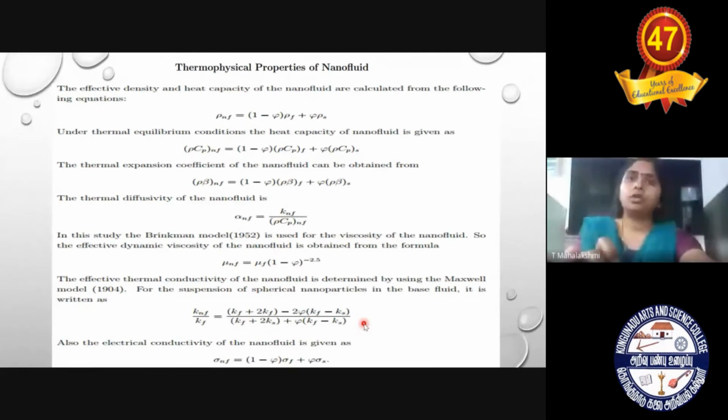There is no need to go with only the numerical calculations, as the dynamic viscosity and thermal conductivity can also be calculated by using equipment. Dynamic viscosity is calculated by using the Ostwald viscometer, and the thermal conductivity can be calculated by the HRT series thermal conductivity measuring equipment.